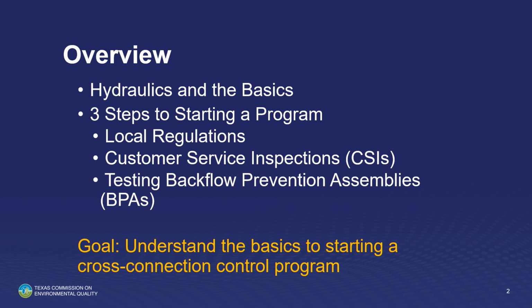So the overview: we're going to talk a little bit about hydraulics and the basics. We're going to talk about the 3 steps to starting a program, which is very important. Local regulations. TCEQ gives y'all a lot of leeway on the regulations that y'all can do. And then customer service inspections. Y'all are the eyes and ears of the utility when y'all go out there. You guys got to just look at everything. We can't miss it. Testing the backflow prevention assemblies. That is very important. We do that all over.